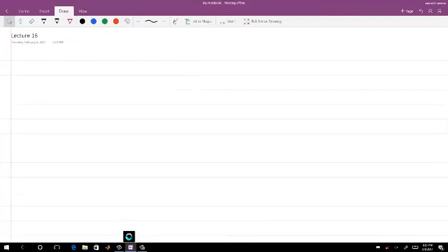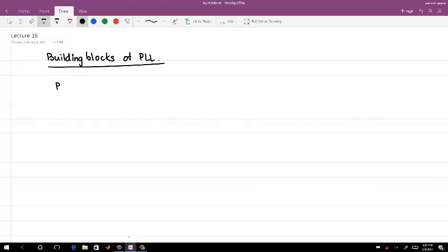Okay, so this is lecture 16, and we were looking at building blocks of PLL, and we will continue our discussion on phase frequency detector. And we saw one kind of phase frequency detector, which was NAND based PFD, and we found that because of the finite T reset time, you have a region